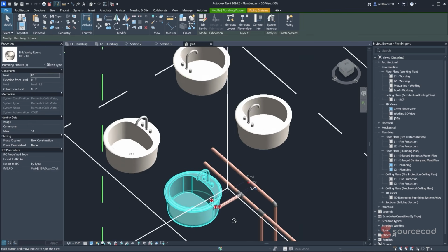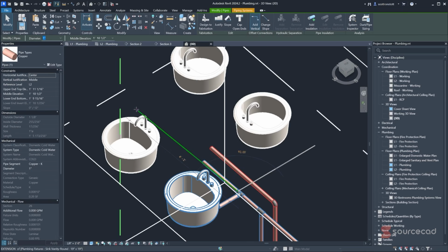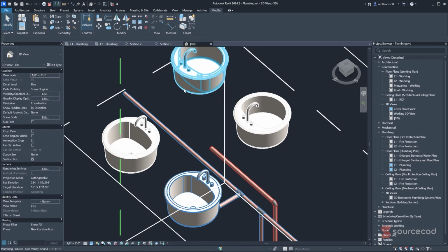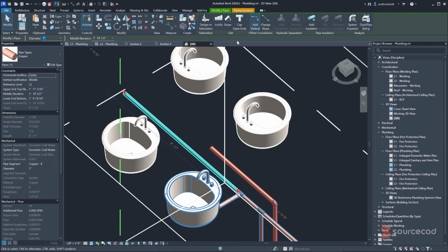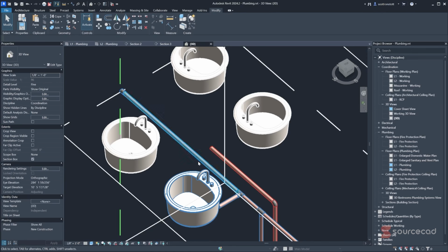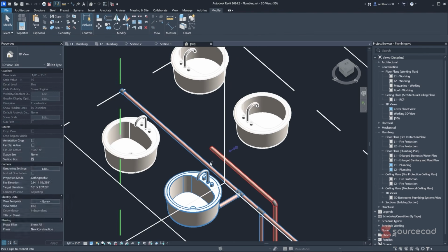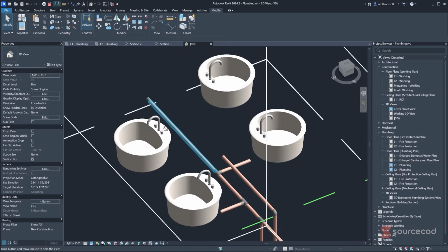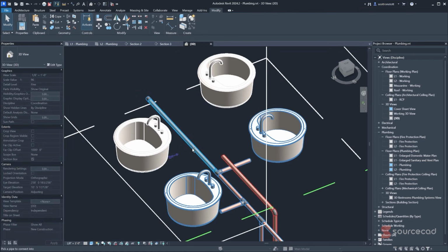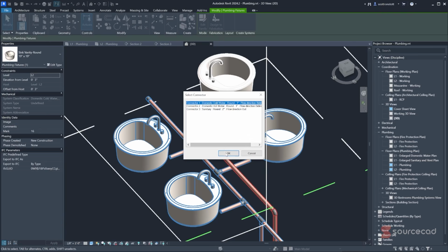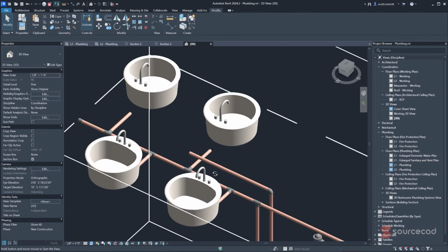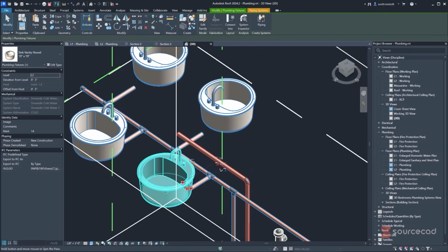Okay, so then over here, we can elongate this pipe. And so that we don't have any connections that route around here, I'm going to select this particular pipe and click Cap Open Ends. So it's going to temporarily put a cap on the end of that pipe. That will make Revit find us a routing solution that doesn't involve going through the end of that pipe. I can select the next sink and click Connect Into, choose cold water, and then click on the cold water pipe. That's looking good. Next. And finally, this one. So those are all straight shots. Very easy.